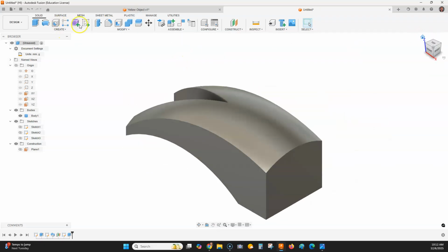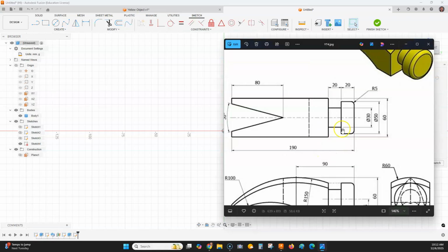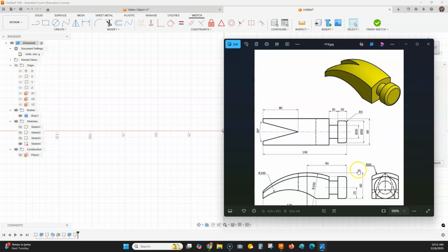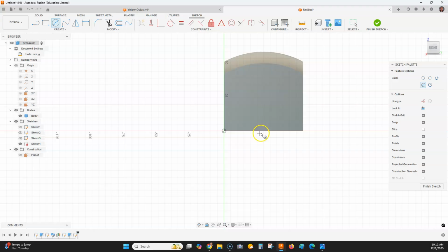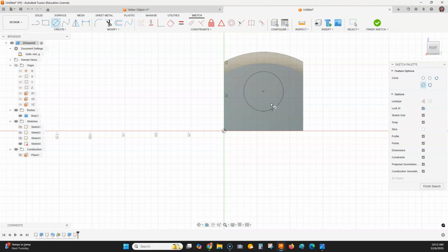Let's click on our sketch. Let's go right back in here and take a look. Now let's make sure we get the location correct. It says it's up 25 from the bottom. It looks like it's in the center, but we can just make 100% sure by referencing our line down here. I'm just going to reference the midpoint, and I'm going to come up and click, and drag out, and it said our diameter in this case is a diameter of 30, and I'm going to hit enter.